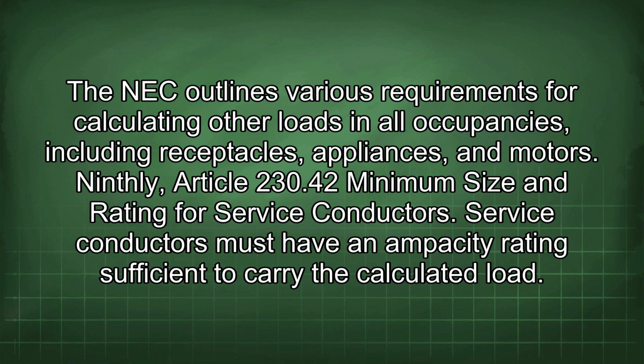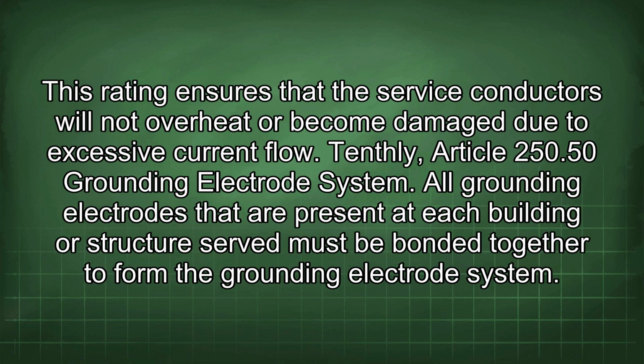Ninth, Article 230.42 Minimum size and rating for service conductors. Service conductors must have an ampacity rating sufficient to carry the calculated load. This rating ensures that the service conductors will not overheat or become damaged due to excessive current flow.